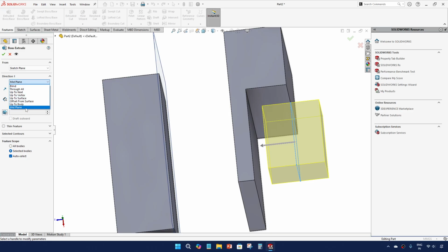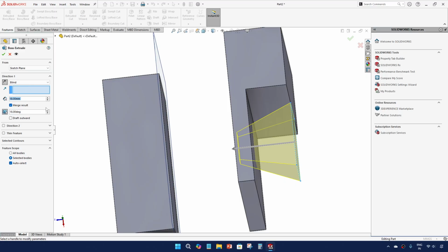So in this, all the options are explained, and this is the extrude direction as I told before, and this is the draft. So how much draft do you want? It's an angle. So just to make it clear, I'll give one side. This is the draft. If you want it outside, you can give outside.